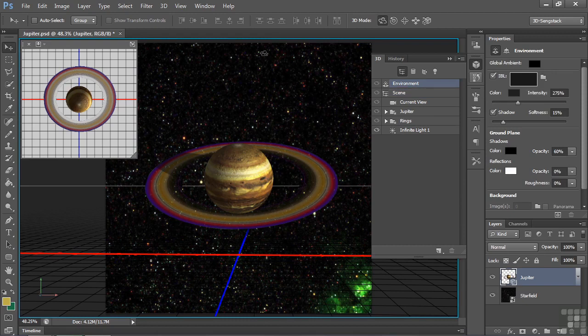Environment basically describes what's around the outside of a 3D object in terms of how this thing relates to the environment. Frequently, you'll put a 3D object in a location, and you want that 3D object to take on the color and lighting of that location, so you use the environment properties to do that. So you have something called an image-based light here that gives it a light based on the image that you can put around the outside of it. Kind of like putting something inside a giant globe and having the globe sort of shining down on that 3D object. And you can control the lighting here.